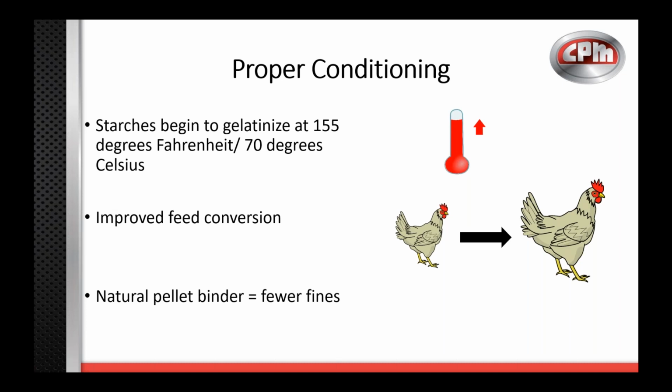So there will probably be a limit or a threshold that you can get to due to our heat coming from our steam. And if you're adding more and more steam, then the moisture of your product is going to increase, and eventually you might see a wet choke or your pellet mill plug. So it kind of depends on the product specifically, but it might just come down to, again, time. As the starches break down, they tend to have their own natural binding characteristics. So as they break down, they become more sticky, resulting in maybe a better pellet quality and fewer fines that you might see.